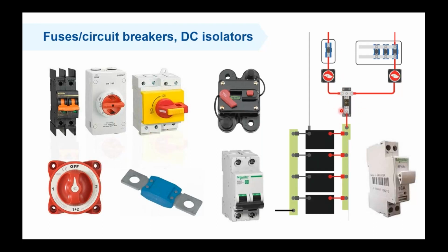And there are time ratings for the fuses as well. So no matter if the cables for a short time are getting 1.5 times the maximum current, then the fuse will start to blow and trigger, and then the cables will be safe, of course.